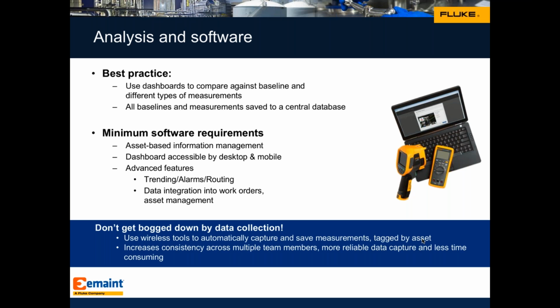That being said, you can sometimes be overwhelmed by the amount of data that's coming back. And I think as you establish a preventive program, it's important to say, what are some key data that we absolutely need to look at? There may just be three types of data that you want to look at: times of running, machine repair time, and so forth. And that's up to you to establish based on the preventive maintenance work that you need to do. But really it's the ability to have the data downloaded wirelessly if at all possible, and captured automatically, and do this on a constant basis, on a regular basis.